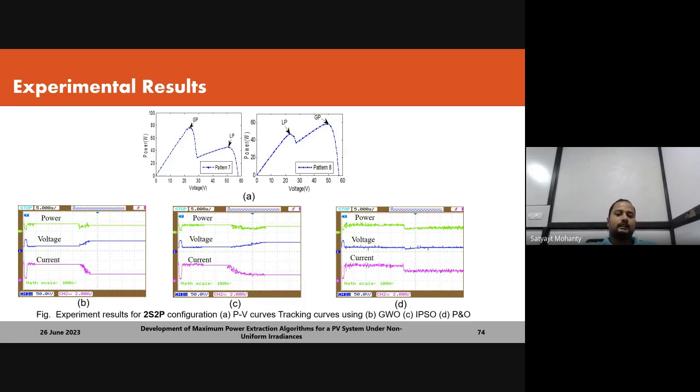So this is a part of a decentralized microgrid. You can take this as a challenge for the DC-DC. If you have solar photovoltaics and a battery, you can connect a buck boost converter. You can take care of this, and you also have to take care of the current fluctuations. For that you can work on the droop control side. Overall this is a booming area, and this can be applied in electric vehicles.